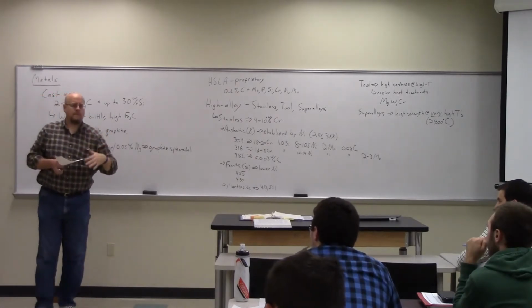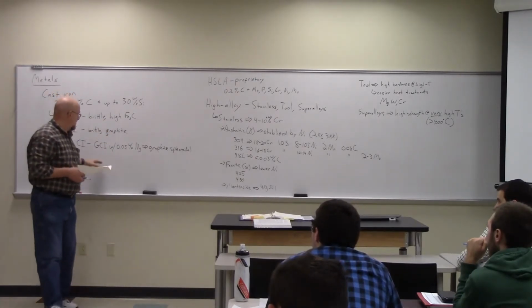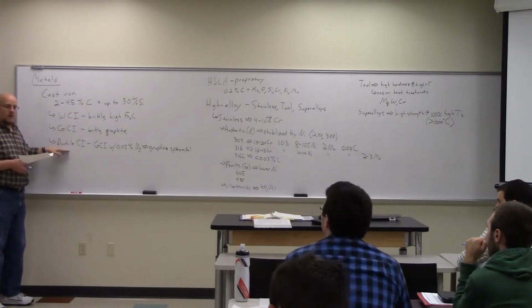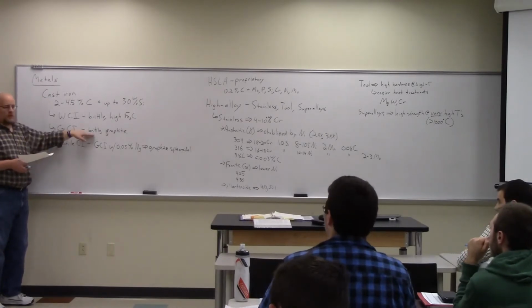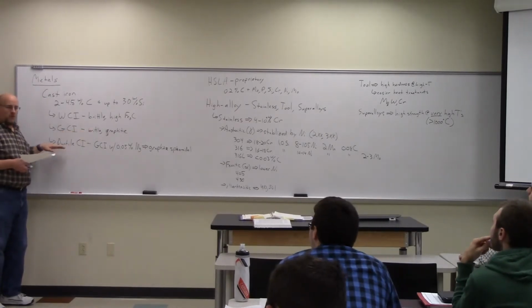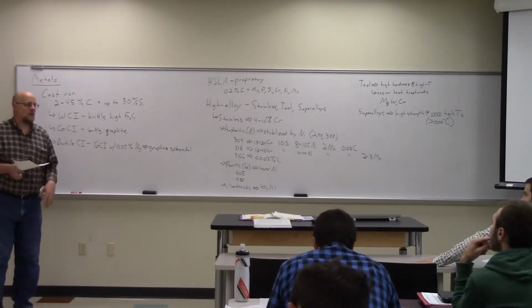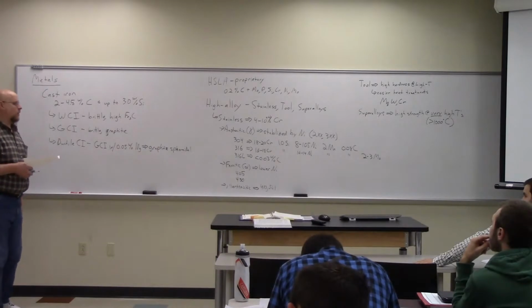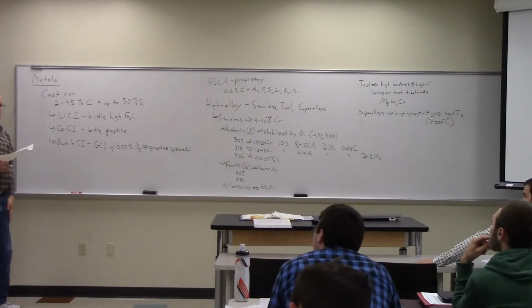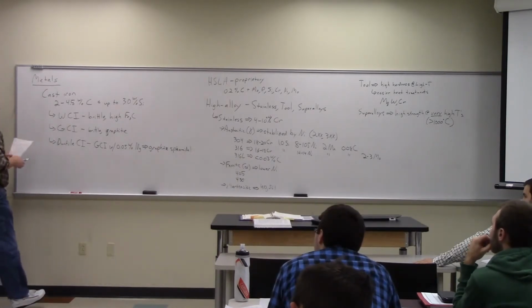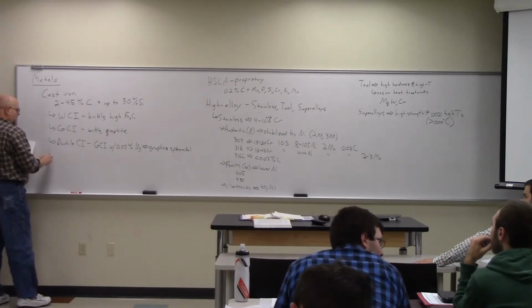Do we want dislocations to propagate? If we want it to be ductile, yes. Right? If we don't, then it's brittle. But if we want it to be ductile, then we have to add a little Mg to get it to form those spheres. Are those spheres buckyballs, or are they like? No, they're just spheres. Nothing as elegant as that.